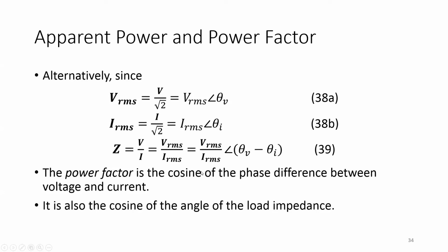The power factor is the cosine of this phase difference between voltage and current. It is also the cosine of the angle of the load impedance. Both statements are equally true and equally valid.